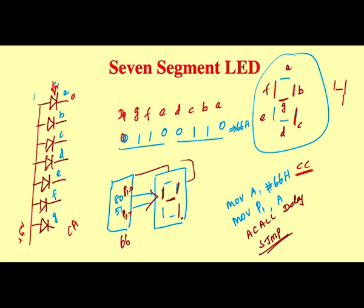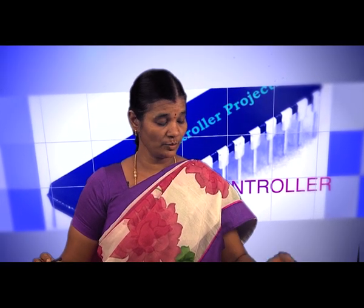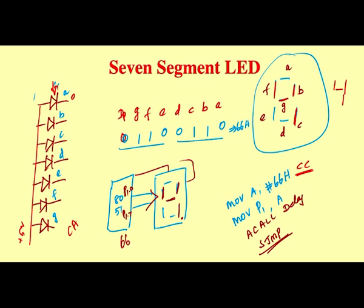Now, you apply 0 volts to switch on the LED. This kind of configuration is called a common anode configuration. By this way, we are planning to switch on the corresponding bit positions, or the corresponding LEDs. Suppose I write the alphabet A, B, C, D, E, F, G.